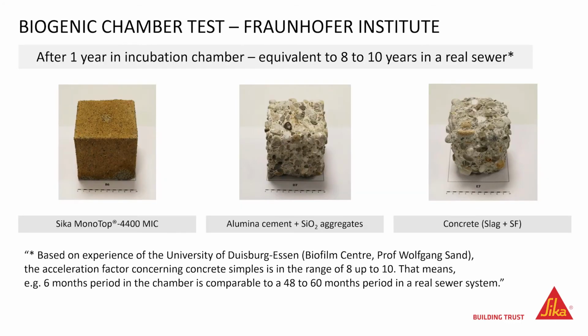These pictures show the aspect of the different specimens after 1 year in the incubation chamber. This is equivalent to approximately 8 to 10 years in a real-life sewer. The picture on the left shows very little degradation of the aluminate mortar. Actually, the compressive strength carried out on these calcium aluminate specimens shows similar values to the reference concrete stored in normal conditions. The other two pictures show much heavier deterioration.